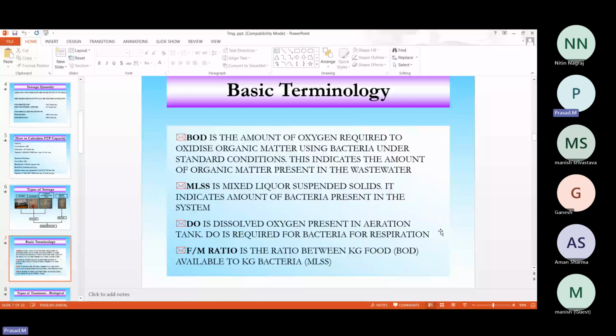When we are sending the offer, at that time we mention only these parameters: COD, TSS, oil and grease, and BOD. But if someone asks for TKN, then we have to discuss with them and suggest what the TKN inlet and outlet will be. At that time we will speak with them.